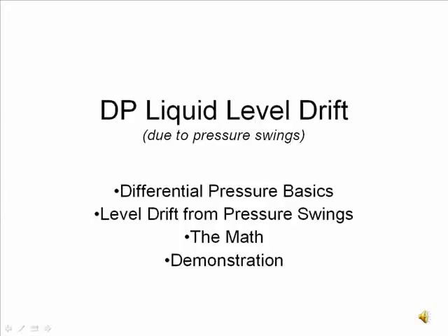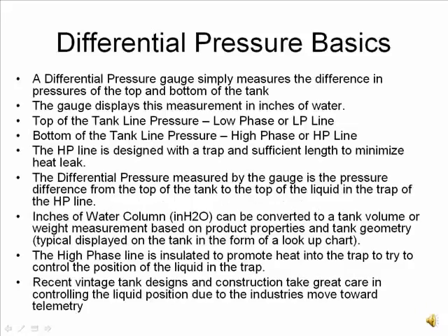This slideshow will attempt to explain differential pressure drift due to tank pressure swings. It will start with differential pressure basics and end with a demonstration. A differential pressure gauge simply measures the difference in pressure of the top and bottom of the tank.